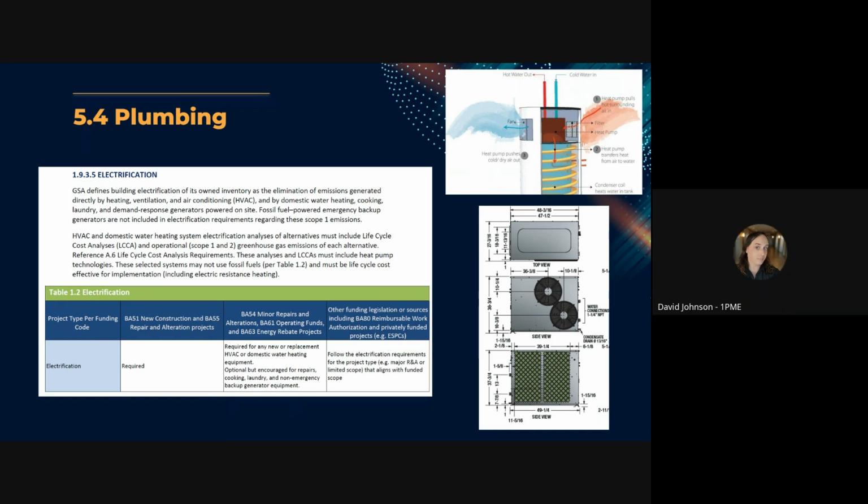David, go ahead. Yeah, not to go down a rabbit hole, but then you got to put your boiler on the generator and it triples your generator sizes. So up in north, you're probably just something to think of. You got to remember that besides the fact that the electric boiler has a COP of 1, which is terrible compared to the heat pumps, they also need to be on the generator, and the generator needs to be sized for your full heat load at that point. And we're one of those courthouses, Mark, and that was the whole discussion between the two options.